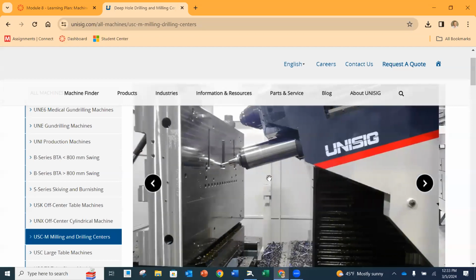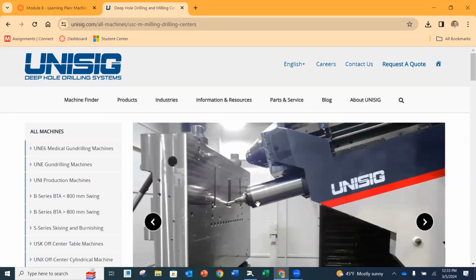These are big milling machines that we made, and this is a machining spindle. I imagine most of you are familiar with that, but this is like a 50 taper CAT 50 machining spindle. At the end of it, a tool rotates, right? So you can cut material and remove material from steel. You all took manufacturing processes, so you have an idea.